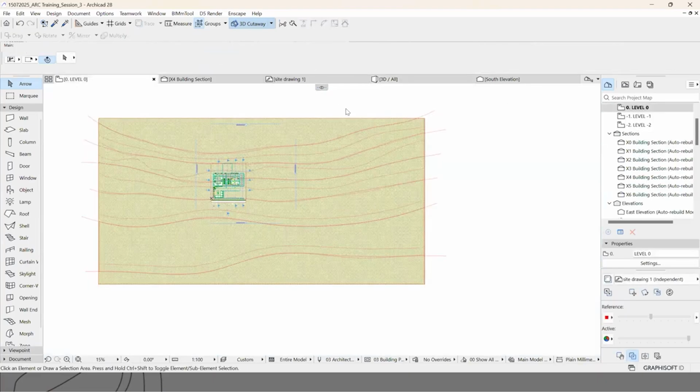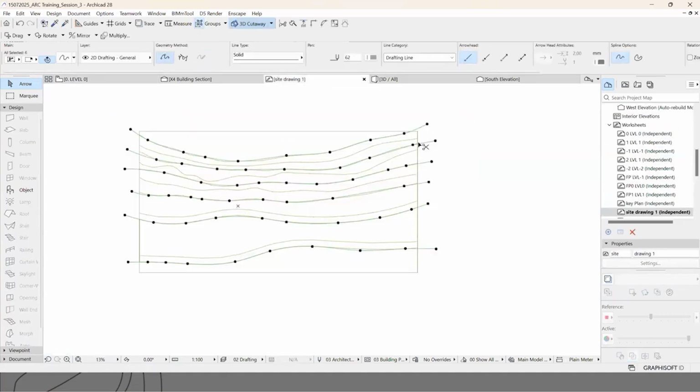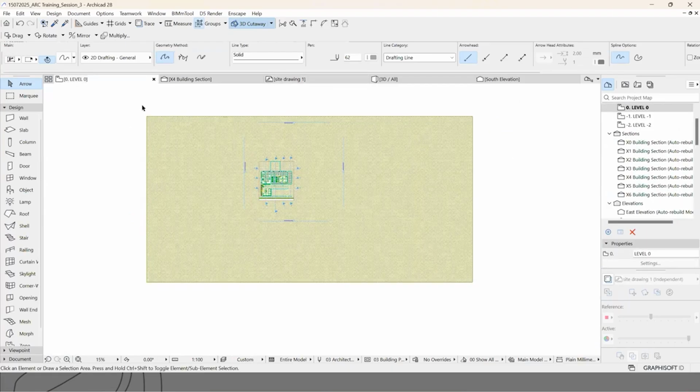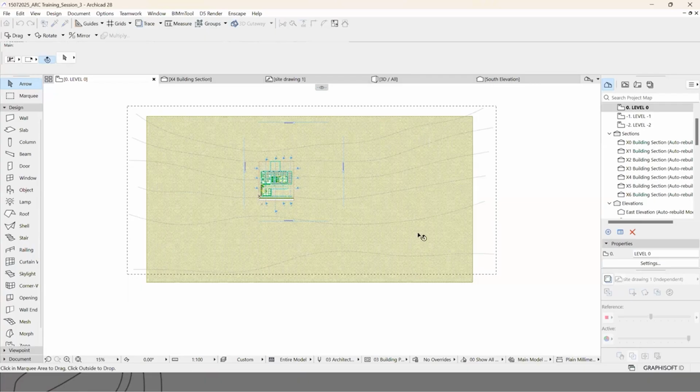And I'm going to do a different action here that is going to select all these splines and do a copy, that is Control C, and do Control V, that is going to be a paste. Only thing is that I need to make sure the lines are here to do this particular activity, and it's going to be easy for me, and later I can delete it also.